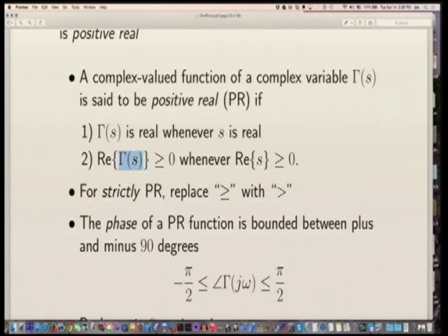So what you're looking for here is the damping, the portion of the admittance that dissipates energy, which is its real part, and that has to be a positive real part. So intuitively, we're just saying that the real part of the admittance is positive, meaning it is going to dissipate energy, it's not going to create energy.